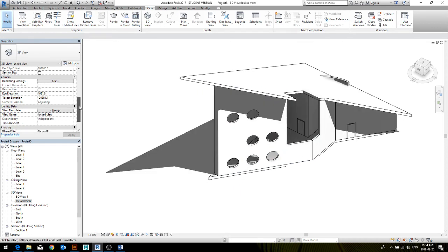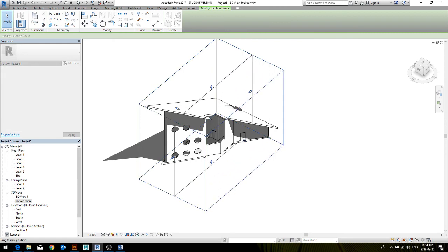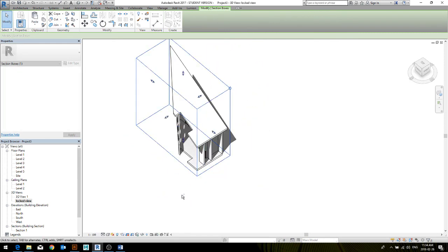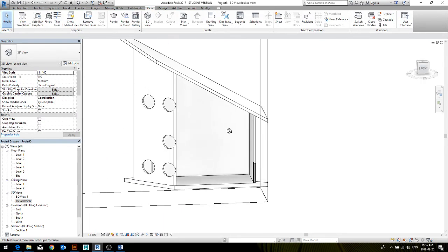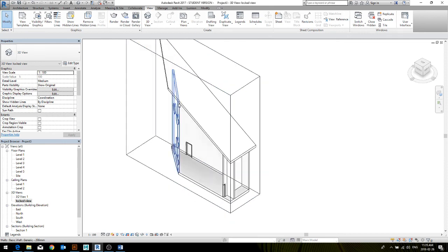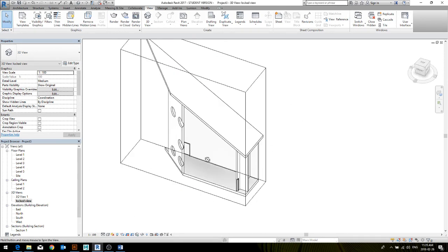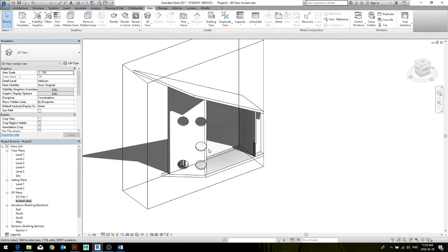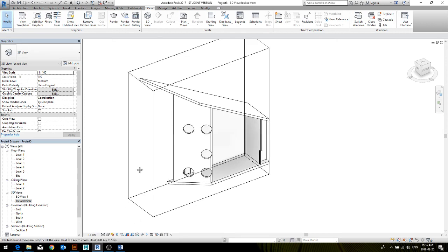Okay, two more things. I showed you guys this quickly last time that in the 3D view, there is this section box tool that is interesting, and it will basically give you a box that contains your project, and you can move different edges to get cuts in your geometry and present or study your model with those cuts. You can keep them and present these as views, but it's also interesting that if you export this 3D view to something else, it will include the cuts. So it will only export the portion that you can see. So let's say I want to render this as a 3D cut object, and I want to take it to 3ds Max or Maya or Rhino or whatever. I can just export this and it will give me all the cuts. That's pretty interesting.